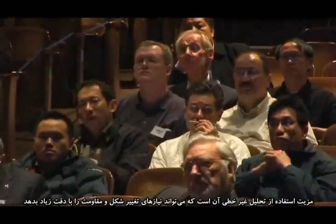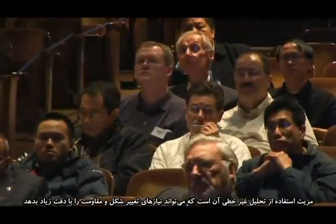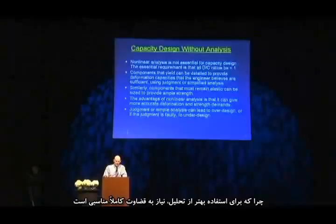The advantage, though, of using nonlinear analysis is it can be more accurate. It can give you more accurate deformation and strength to mass. Judgment or simple analysis can lead to over-design, and if the judgment is faulty, it could lead to under-design. And nonlinear behavior is pretty tricky. If you're not going to use analysis, it does require some pretty good judgment.